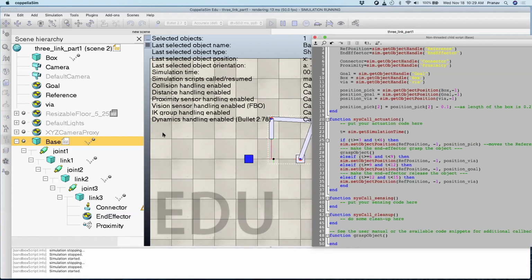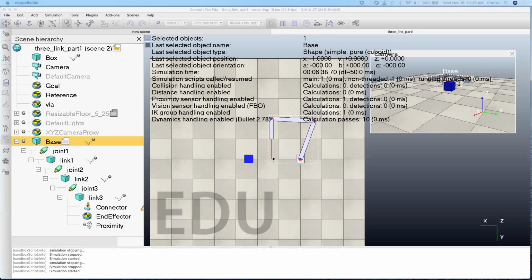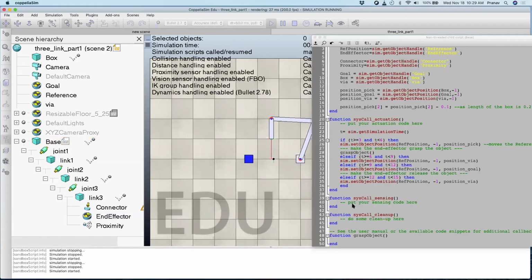Okay, so this is something which is new and sort of the way CoppeliaSim works. What needs to be done here is, when the manipulator is over here, it needs to figure out what shapes it's able to pick up. Right now, in this case, there is the manipulator, there are the 3 links, 4 links to the manipulator. Then there's the blue box, and all those shapes are valid shapes, right? But it should know that this object is the only one that is to be picked.